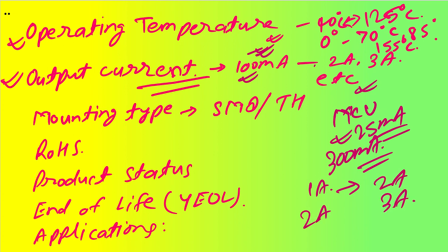If you need 2 ampere rating, then what will you do? Still you don't have to go ahead with 4 amperes or 5 ampere. You can still manage with your 3 ampere regulators, but here you are going to deal with more than 200 or 300%, but here 50% is more than enough. So for lower current applications, you can go ahead with more room, like 100% more or 200% more. But for very high current applications, even 50% is enough. Okay.